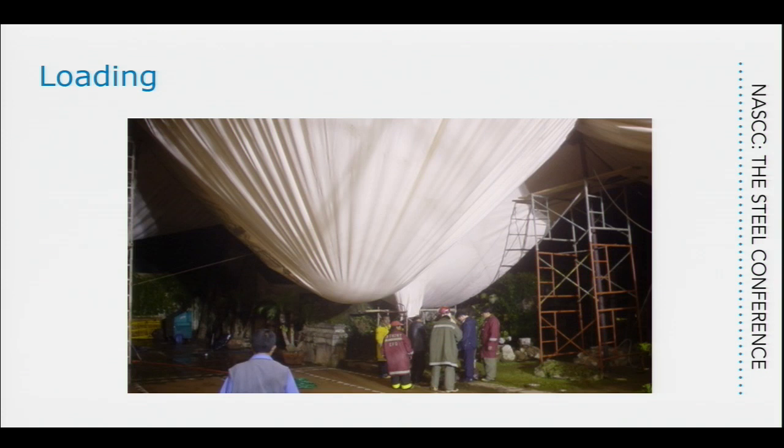Yes. On the cube, it seemed like after a couple of years, the quality deteriorated. Was that because of dirt in the air getting inside the cube? Yes. Well, no, not inside the cube. Usually outside. Depending on how good a care they take of the facade, it lasts more or less. ETFE will last for a long time, and there's different qualities of ETFE. Part of the problem is pollution there. It rains, and acid rain is fairly damaging depending on the caliber of ETFE that you use.